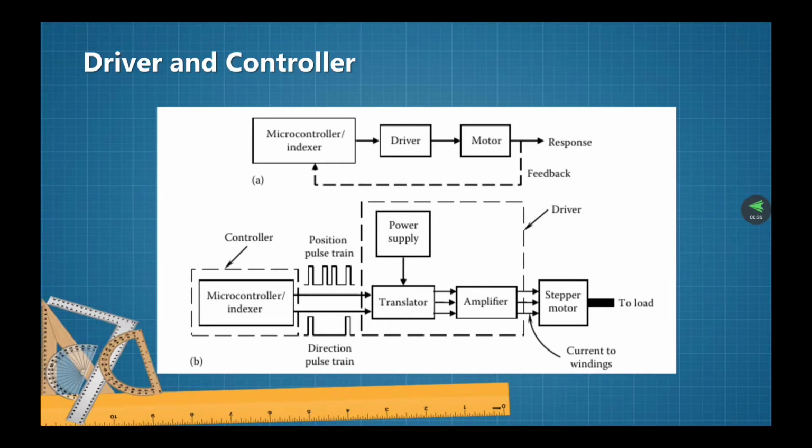As a result of the step size, whereas it is an incremental synchronous operation, open loop operation is adequate, at least in theory. An exception to this may result under a highly transient condition, exceeding the rated torque, when a missing pulse can be a problem.